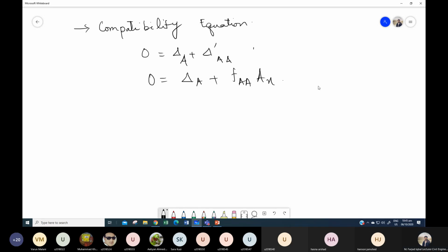For the virtual work method, you remember that the equation for the deflection is integral from 0 to L of capital M small m over EI. If I revise this one, this capital M is the moment acting on the frame when all the external loads are acting. And this small m is the moment equation for the frame when the virtual load of one is acting in the direction of desired displacement.